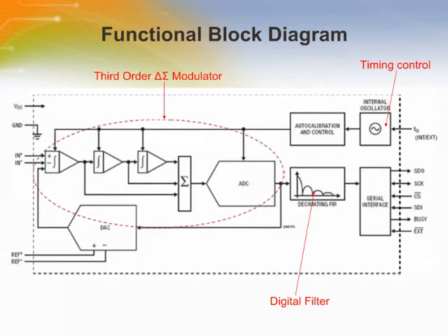The LTC2440 is a high-speed delta sigma analog to digital converter with an easy-to-use 4-wire serial interface. The 4-wire interface consists of serial data input, serial data output, serial clock, and chip select. The interface, timing, operation cycle, and data out format is compatible with the LTC2410.